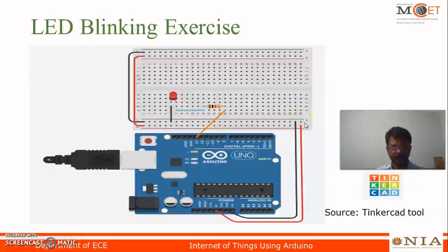First, for learning purposes, you choose the breadboard in such a manner that you have both supplies in their rows: top two rows with positive and negative, and bottom two rows with positive and negative. The basic idea is you need to blink an LED. You connect it to the 13th pin. Basically, the 13th pin has an inbuilt LED. I hope you could see this L and orange color shaped blinking setup. It is an inbuilt LED for every Arduino board.